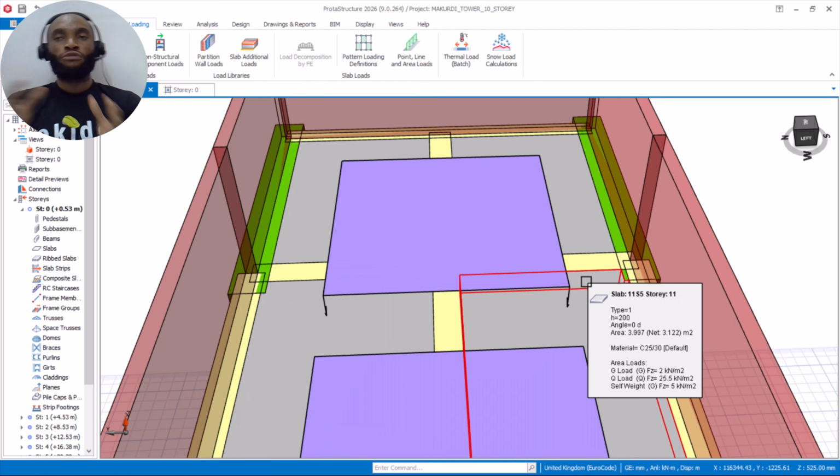So the tank doesn't have any place to shift. So that particular point becomes the place where the load will be on the structure. So with that kind of scenario, it is best to use area load to center the load at that particular area of that particular slab.